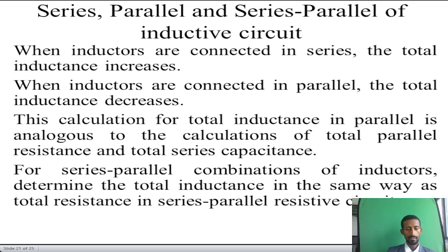Okay, right now we are in a position to talk about the connection of inductors: different connections, series, parallel, and series-parallel connections. When inductors are connected in series, the total inductance increases, like that of resistors. Connected in parallel, the total inductance decreases, like that of resistors. This calculation for total inductance in parallel is analogous to the calculation of total parallel resistance and total series capacitance.